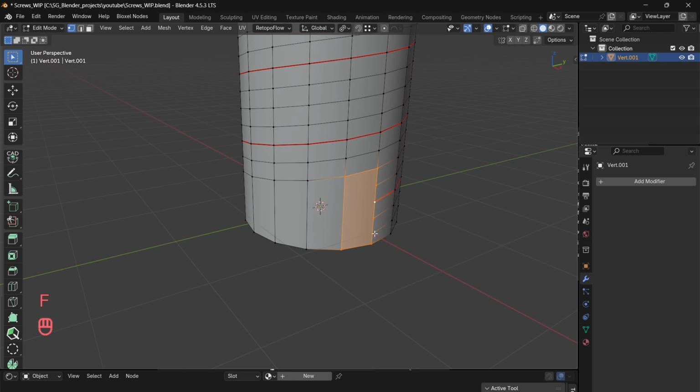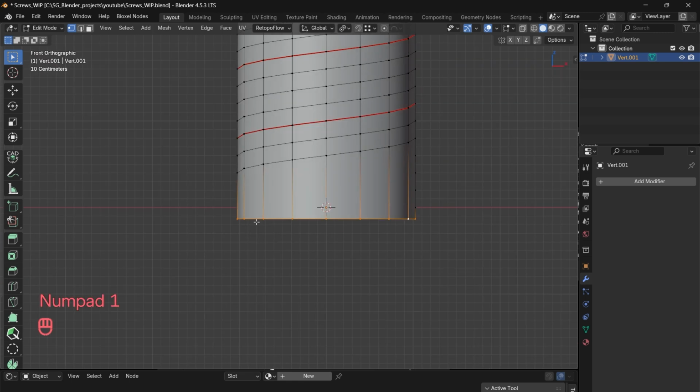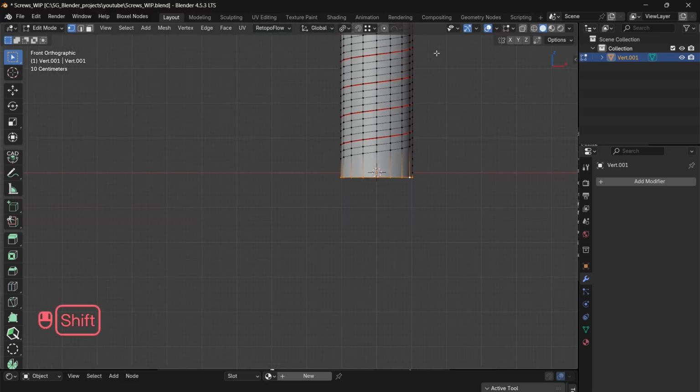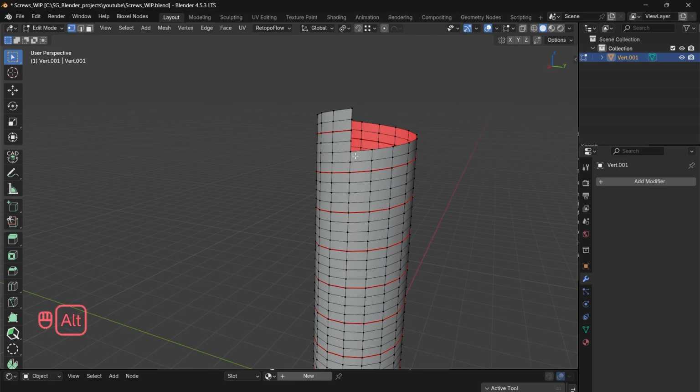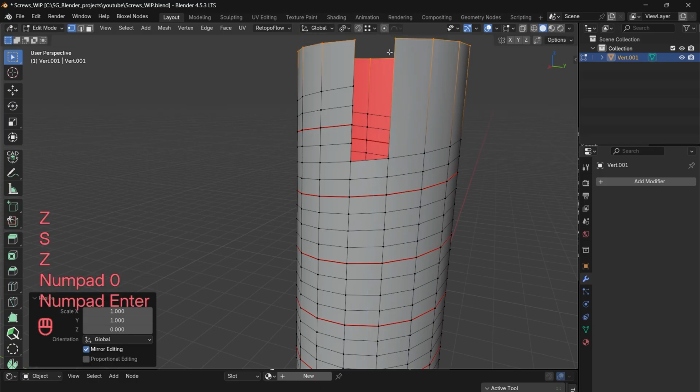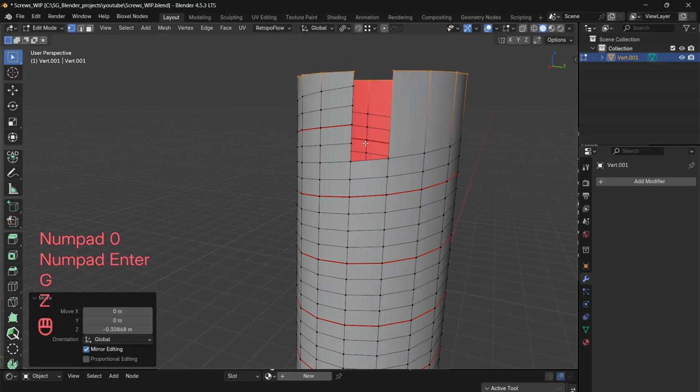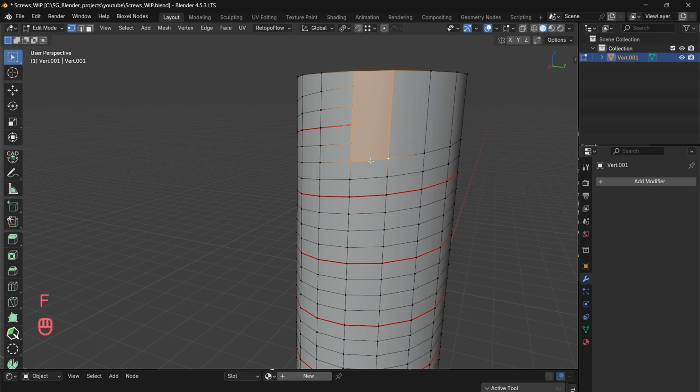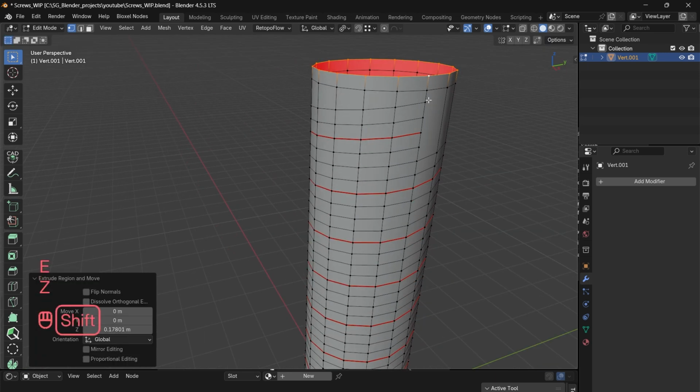What I did, if you look at the front perspective, is make this face touch that XY plane properly. Otherwise, it was just floating in the 3D space. I need to do the same thing on the top part. Let me unselect these vertices, extrude it along the Z axis, S Z 0, G Z, move it a little bit, and let's fill it up. Now I'll extrude it again, just to create a buffer loop here.